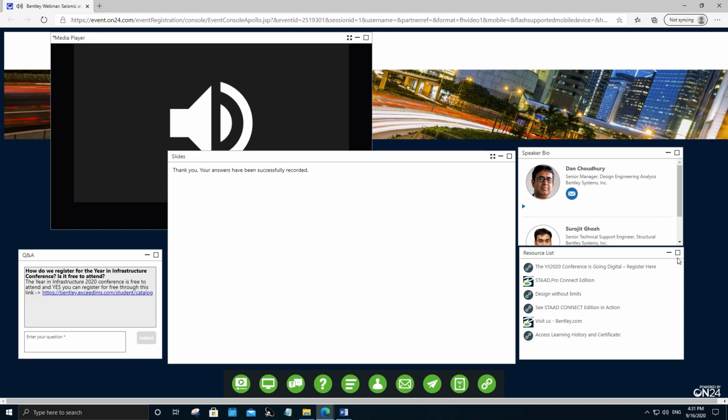That is, you do not actually need to do a dynamic analysis for that mode. Or in other words, dynamic amplification will not be possible in that mode. So you can consider those modes as the missing mass modes, and statically add that to the response spectrum analysis that you have obtained for the structure.